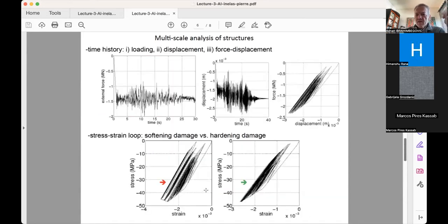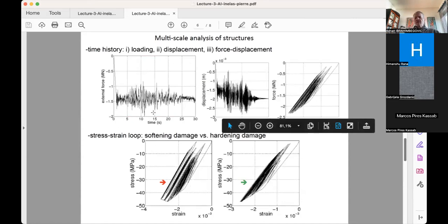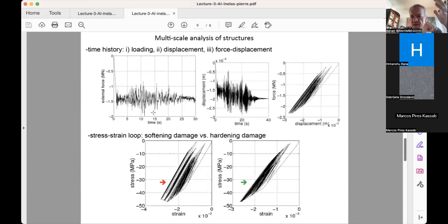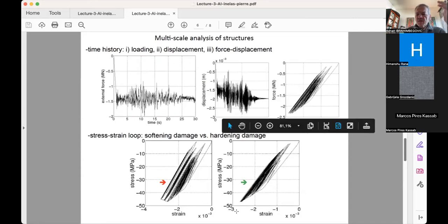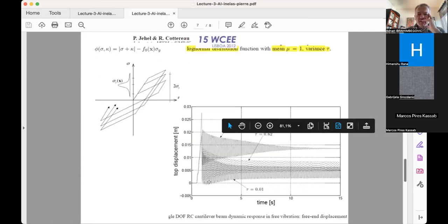So if you take a simple loading program, you can see a difference in shape, but not necessarily in dissipation. But typically, recall that what we are really running is some kind of stochastic loading, which varies in time. And for this type of loading, if you want to talk about safety, you had better be able to prepare an estimate of the performance of the structure in terms of whether you are over the board or not. That means whether you are going into softening or not, and then you can get a little better estimate of the safety.